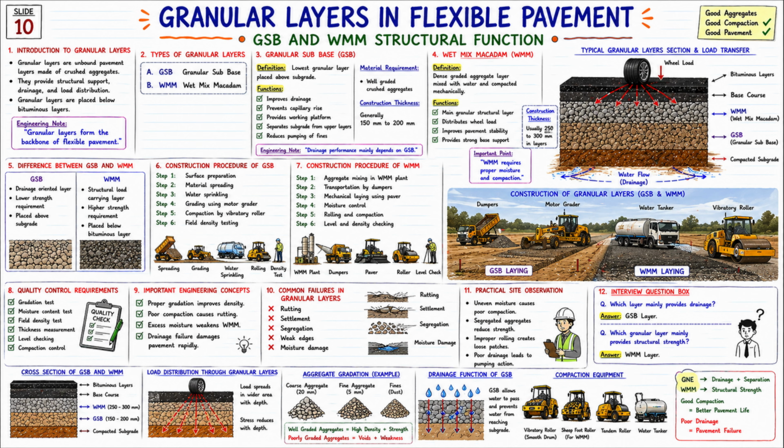Now let us look at the eighth topic. Quality control requirements. Quality control is very important in granular layers. Which tests are required? Gradation test, moisture content test, field density test, thickness measurement, level checking, compaction control. If these tests fail, pavement performance is directly affected.